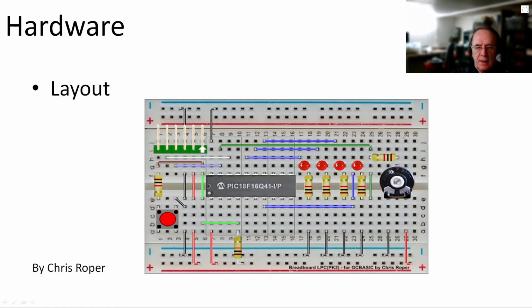As I've just said, I have got the terminal to transmit connected to this pin here, third pin on the bottom on the right. There we go. The TX goes there, and the ground is connected into here. Okay, here we go. Very simple. Thank you, Chris, for the layout.